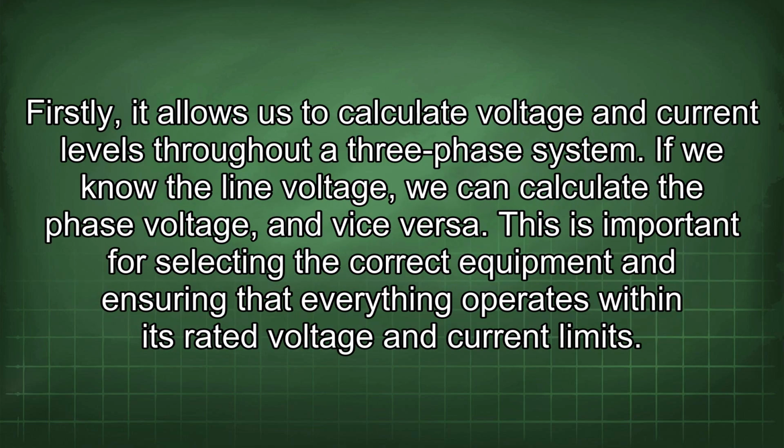Firstly, it allows us to calculate voltage and current levels throughout a 3-phase system. If we know the line voltage, we can calculate the phase voltage and vice versa. This is important for selecting the correct equipment and ensuring that everything operates within its rated voltage and current limits.